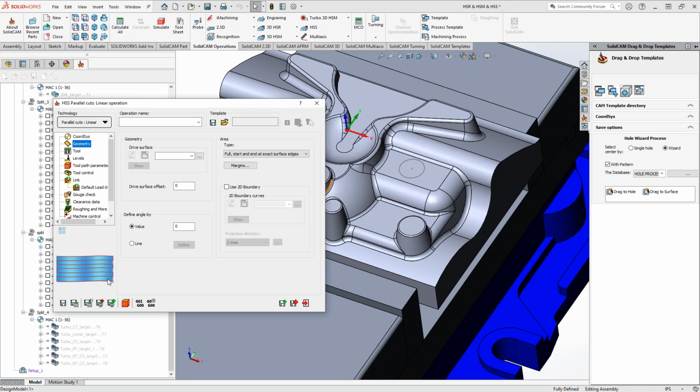Now, if you still wanted to pull back from those edges a bit, you'll notice that as soon as we grab that second option, we get the margins parameter. That allows us to add whatever we want to offset from those edges. But I often use this setting here, because if I'm trying to avoid the edges because I want to avoid something outside the surface, I'm going to use the gouge check.